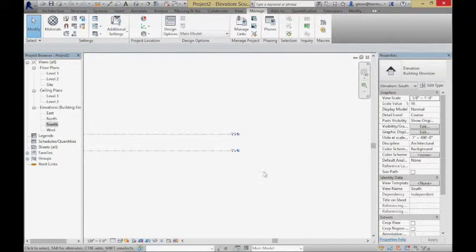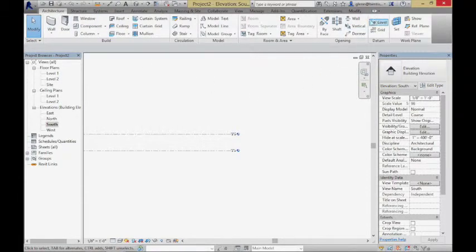Now, we want more than just probably 2 floors. Yeah, as I'm thinking about this building, maybe it could be up to 10 stories. I'm not quite sure. So I'm going to add some more floor levels in there that'll let me be able to handle that sort of a case. And how I do that is under the Architecture tab. There's this tool which lets us create levels.